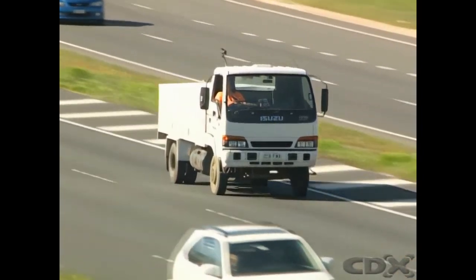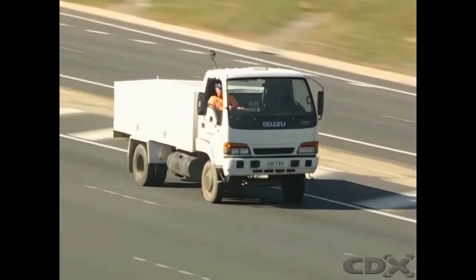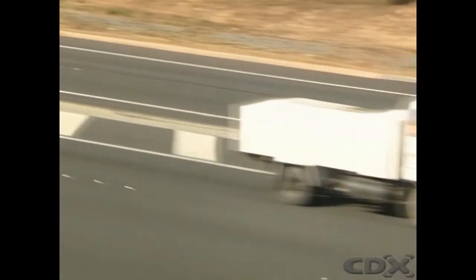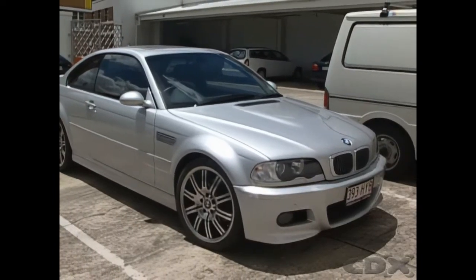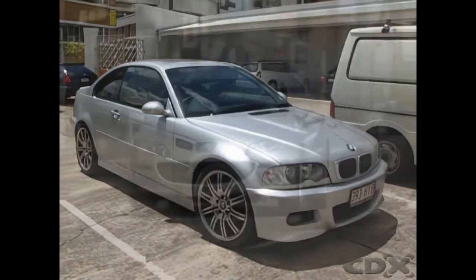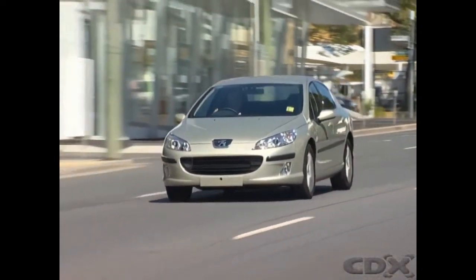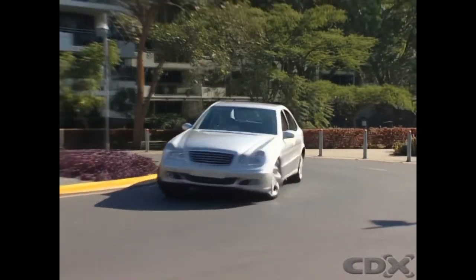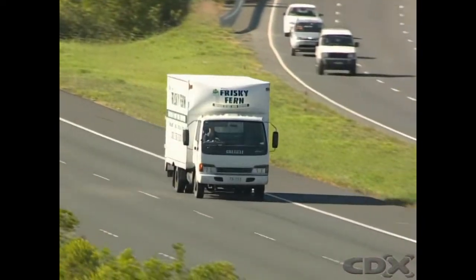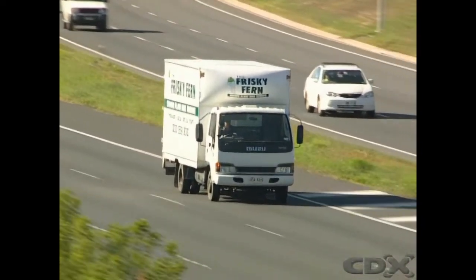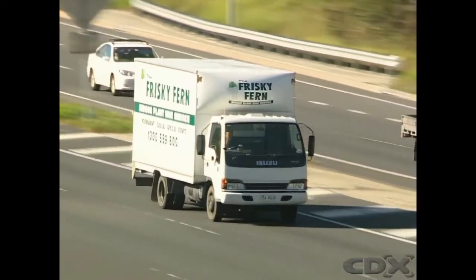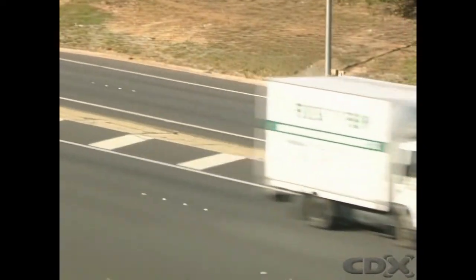Dual mass flywheels are fitted to light-duty diesel trucks with standard manual transmissions and to higher performance luxury vehicles to dampen vibration in the drivetrain. This also allows vehicles to be operated for longer periods without long-term damage. Transmissions in light-duty diesel-powered trucks have a heightened sensitivity to fluctuating torsional inputs.